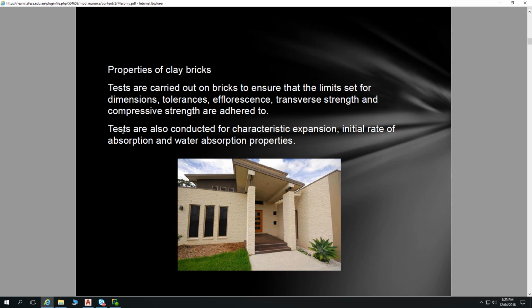So that type of brick is slightly more difficult to lay because you slap the mortar on and it has a tendency to slide off. These older bricks, you slap the mortar on, because they have such good suction, they will hold that mortar, but they'll draw more moisture out of that mortar as well. So the mortar won't be as strong, and it'll also shrink more.